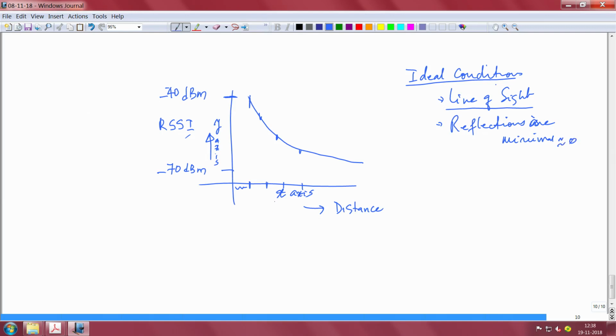There is also one problem with this graph, I can tell you this, that whatever you do in terms of estimation of distance to RSSI, high reliability is achieved only up to some distance, okay, from minus 40 to let us say up to about minus 55.